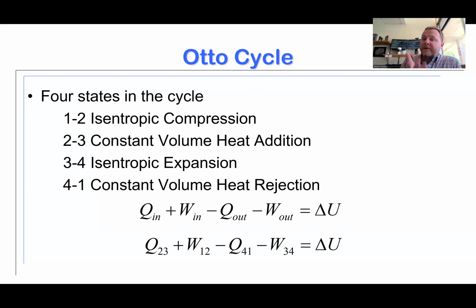Okay, so we saw these in the diagram. Here they are again in words. Isentropic compression from state 1 to 2. That again, it's compression, so that's work in. So we're taking the work in, replacing it with work from 1 to 2.